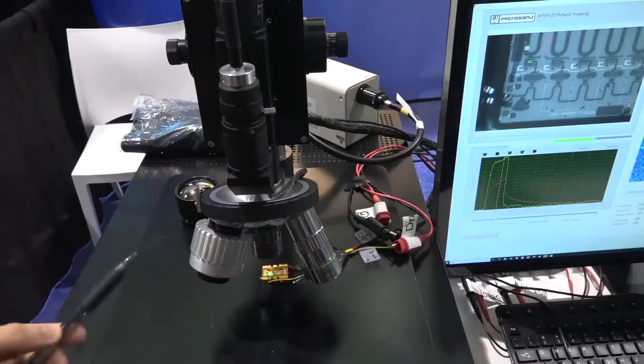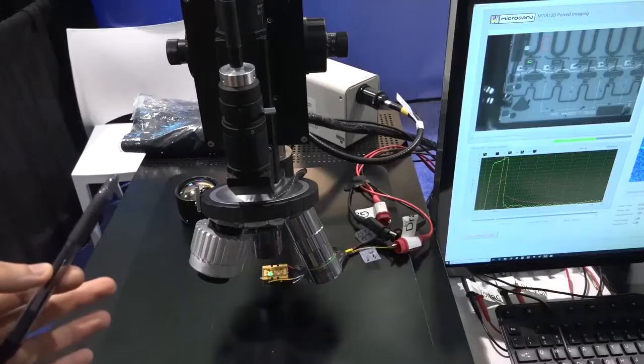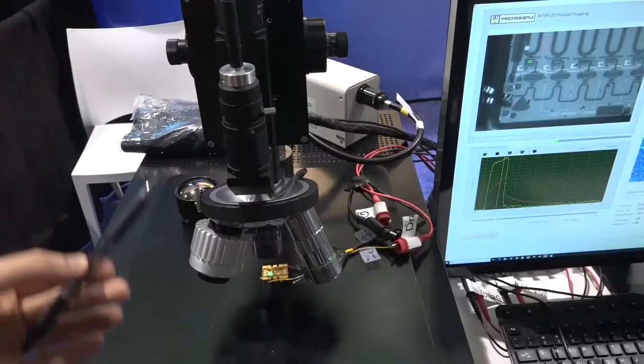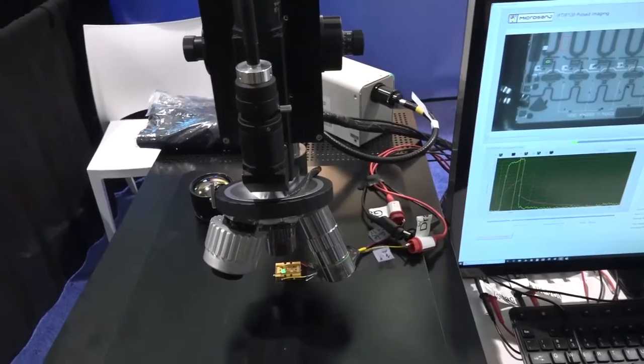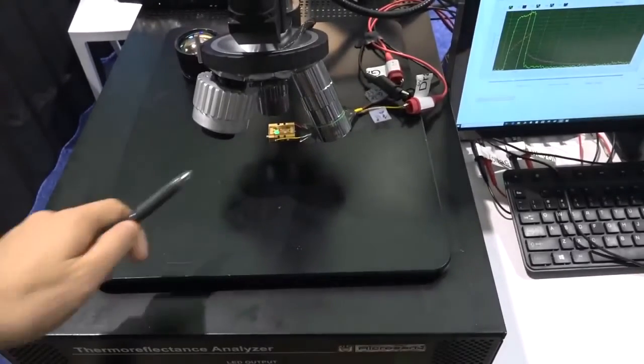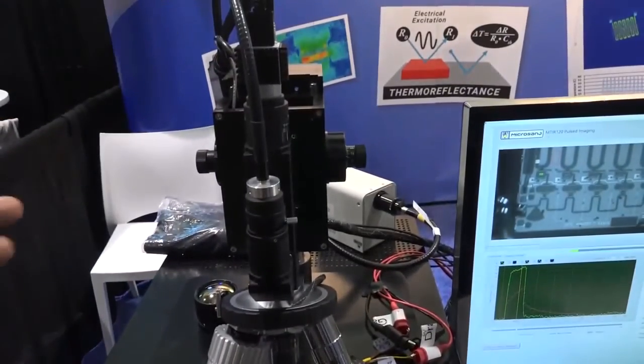You don't need a thermal imaging system that is designed to operate at several micrometers. You are operating in visible light, which means all of your microscope devices and components are operating in visible light. You can see right through them as you would normally do with any microscope. So what they do on top of that is that they correlate the shining of this light with a lock-in amplifier that they have designed, connected to a camera up here, and everything here is synchronized together.